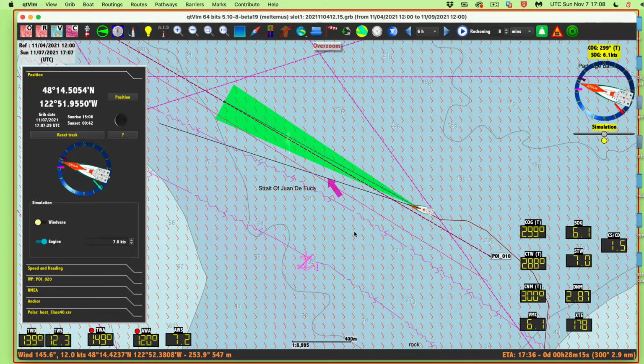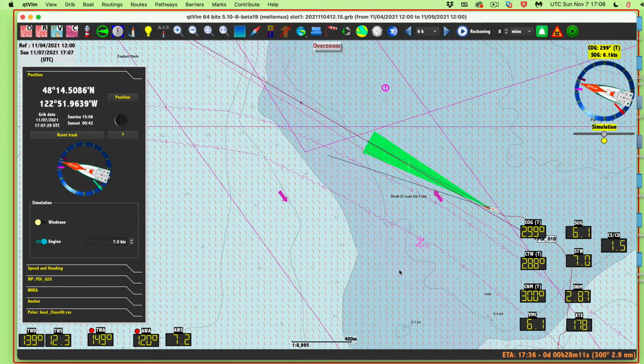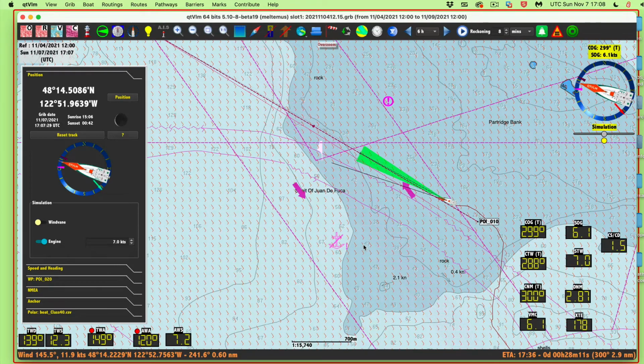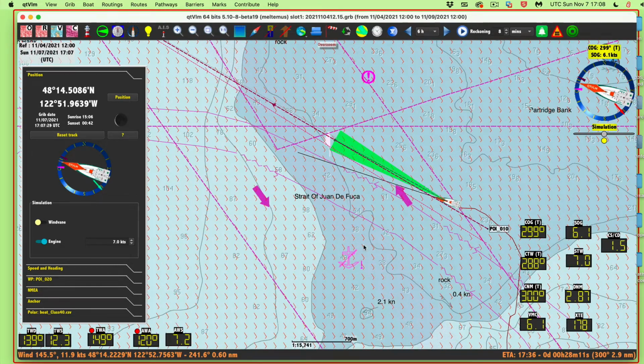Okay, I'm going to leave it there. And this will come up. We're going to do some more actual examples, but this is how you set it up, and the principles of safe navigation. Monitor the heading line. We have a case, and I'm going to put links to it, where we did a simulation or reenactment of the grounding of the Ever Given, the super container ship Ever Given, that ran aground in the Suez Canal. And if you watch that video, you'll see that if there was careful monitoring of these two lines, that may have been avoided.